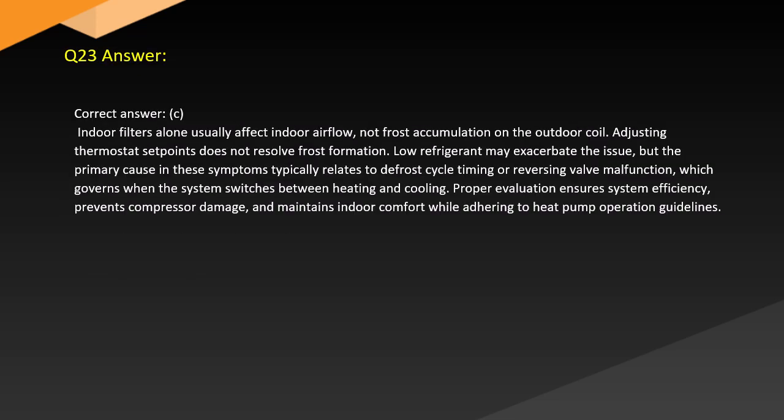Answer. Correct answer. C. Indoor filters alone usually affect indoor airflow, not frost accumulation on the outdoor coil. Adjusting thermostat set points does not resolve frost formation. Low refrigerant may exacerbate the issue, but the primary cause in these symptoms typically relates to defrost cycle timing or reversing valve malfunction, which governs when the system switches between heating and cooling. Proper evaluation ensures system efficiency, prevents compressor damage, and maintains indoor comfort while adhering to heat pump operation guidelines.